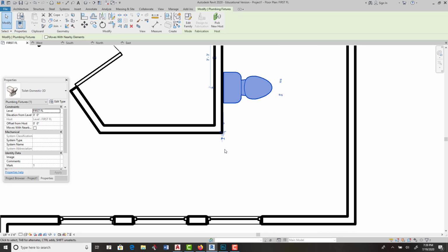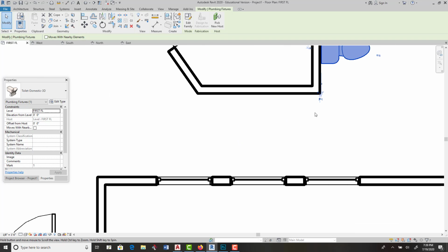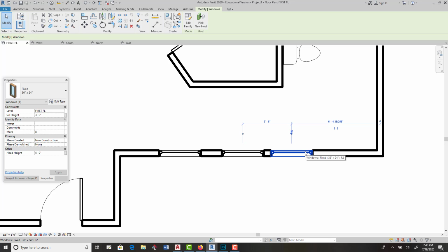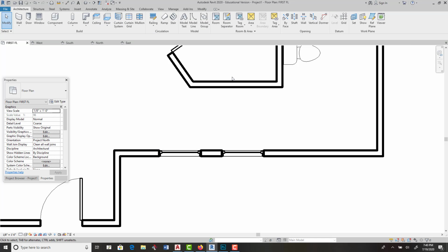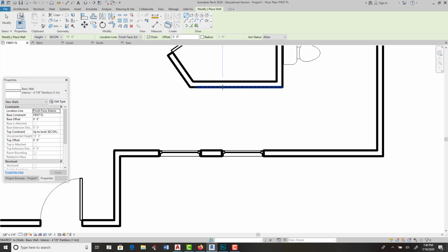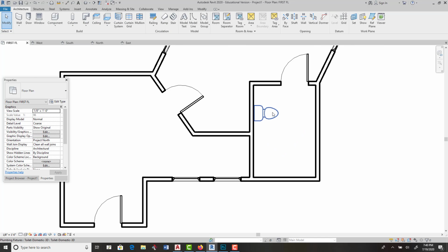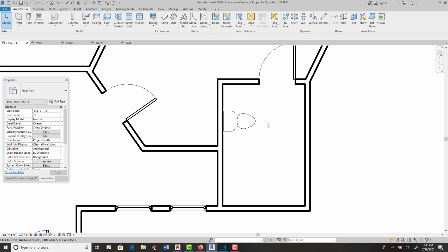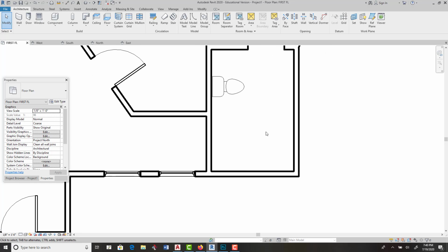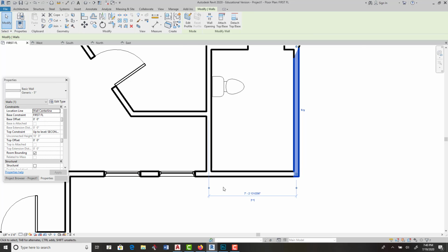And let's close off this bathroom. Let's add a few more walls here. Maybe we have to get rid of this one for a second. Let's get rid of that one. Okay, good. Let's go back to wall, architectural. And there's our wall. And remember, okay, good. And we'll escape. There we are. So now let's make sure this is 5 feet so we can have a bathtub. So we will, it's 7 feet.